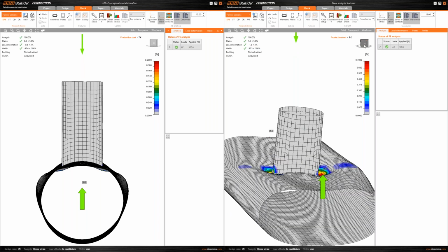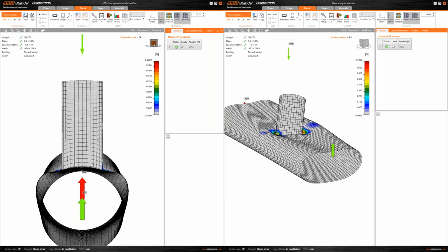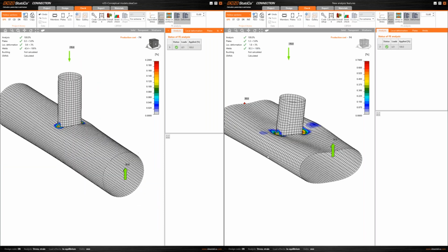Now, beside the length, the difference lies in the condensed super elements that allow this member to deform. In the previous version, we were moving the member to the end using constraints. However, these constraints were also constraining the member from deforming, and we had an impact to the region of the connection.